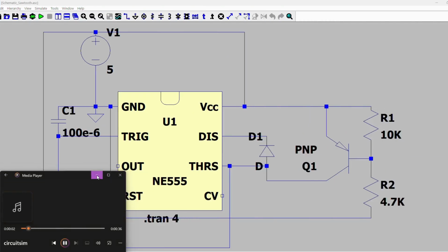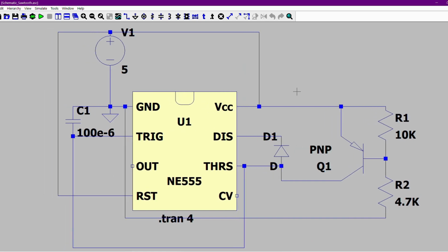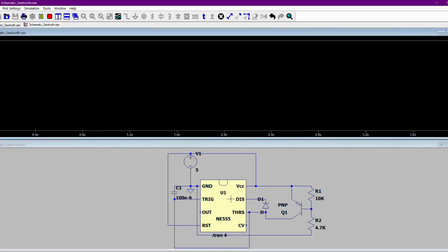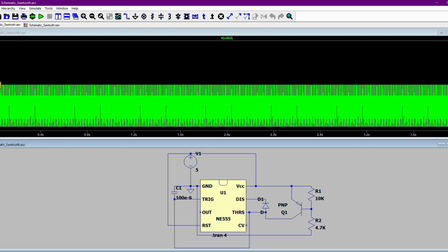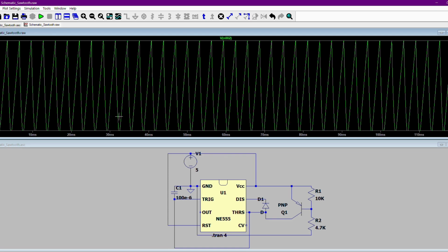In this simulation phase, we examine the LTspice circuit simulation, which bridges the gap between mathematical theory and physical hardware. The circuit utilizes a constant current source to charge a capacitor, ensuring the voltage rises in a perfectly linear ramp rather than a standard exponential curve. Once the threshold is reached, a rapid switching mechanism triggers an instantaneous discharge, creating the characteristic flyback effect. This stage is essential for identifying real-world constraints, such as switching delays and component tolerances, that our ideal Fourier equations cannot predict.